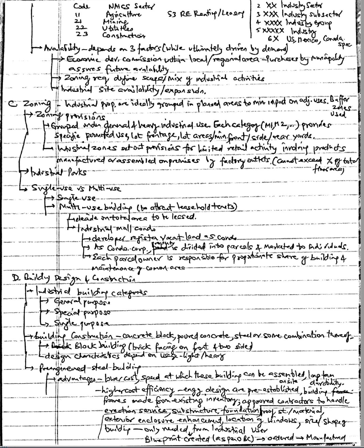Heating would probably be with gas-fired radiant tube heating, with separate rooftop heating or cooling for the office area. Lighting is typically metal halide high bay fixtures for the industrial area, fluorescent fixtures for office, and high density discharge fixtures for external perimeter lighting.